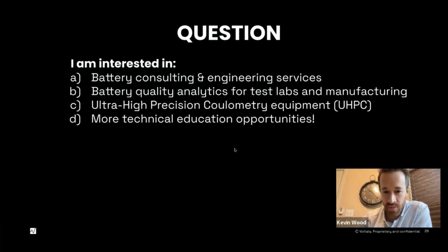There was a question about, do you propose any specific filtering technique to remove any noise or uncertainty of collected data at the end of a test? I responded a couple times to a few different people: you really have to look at your cycler. This is part of the benefit of using NOVONIX equipment, but you have to look at your cycler and see what the resolution of your equipment is. I see a lot of times people are recording at data frequencies of 0.1 seconds and some crazy high frequency data collection rates. And the reality is that if you're recording at too high a frequency, you're just wasting space.